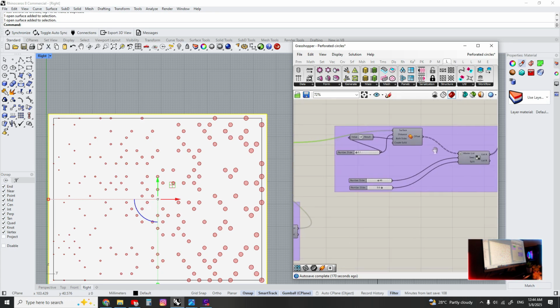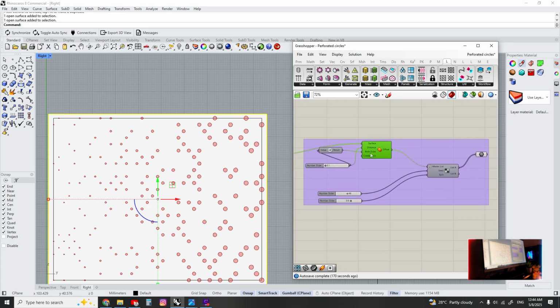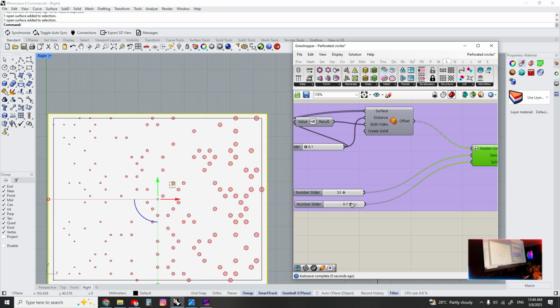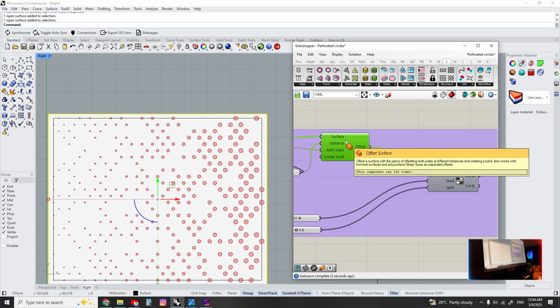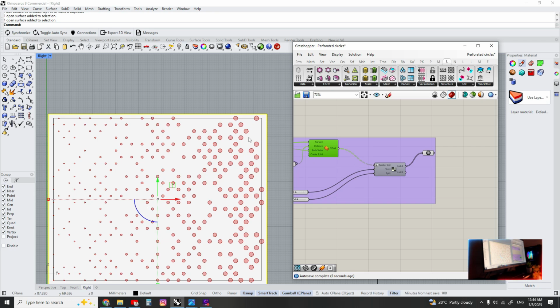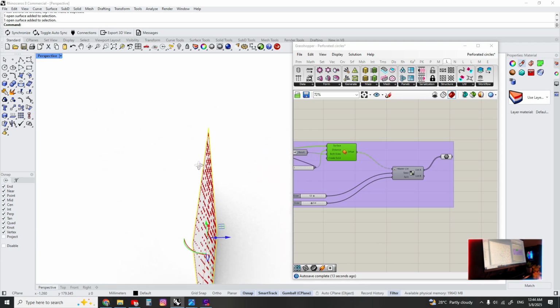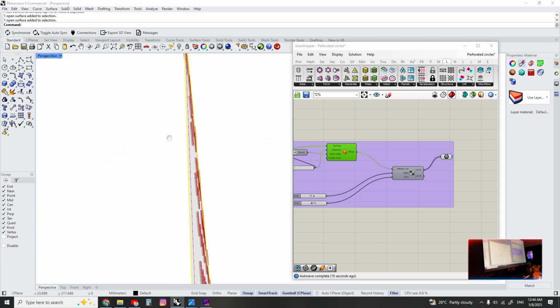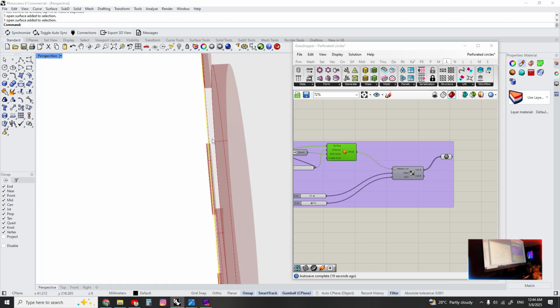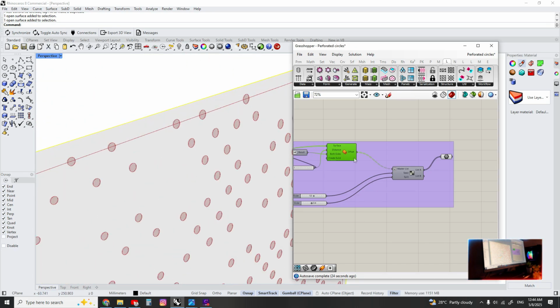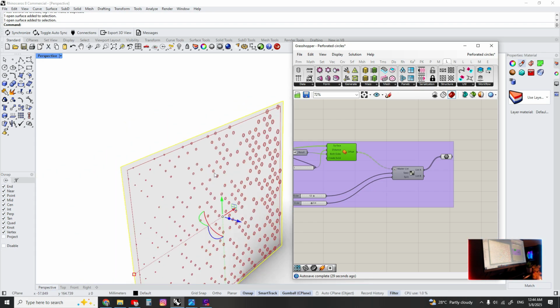And the last part is adding the thickness with splitting randomly. The thickness I added just to cut between the surface base and the model. As you can see, if you want to split an object, you have to make sure that it is extruded in and out on both sides, so you can cut it with no issues.